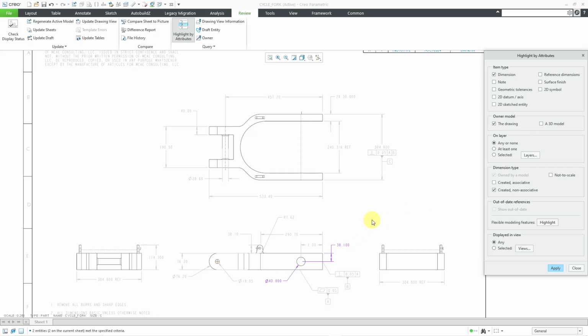And these are actually the ones that showed up with the symbolic form DD followed by a number. These are drawing dimensions. In other words, these are dimensions created for draft geometry. That's another sign that this is actually a sketched in entity as opposed to an actual hole in the model. So that's another good check for your drawings.